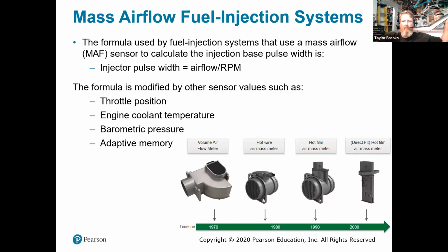Typically, whenever you get any type of debris in the cylinders, it always goes to the back cylinders. That's because the engine's always at an angle downward, so your front cylinders are higher up than your back cylinders, so gravity kind of draws it that direction. And yeah, we absolutely grenaded cylinder number 4 piston, blew it into a bajillion pieces. Because that happened at higher RPM, probably pushing 6,000 RPM, the connecting rod had no more support at the small end, and it buried itself into the cylinder wall, and the engine was gone. There was nothing we could do to save it.